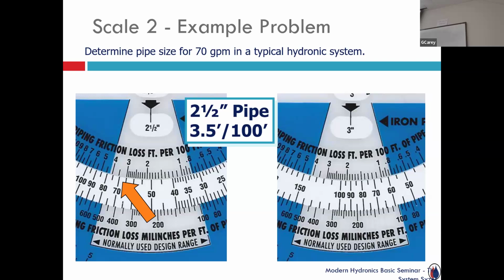So, from an energy consumption standpoint, what's the downside of going to 3-inch? Yeah, cost, upfront costs, installation costs, first costs, all of those. So do I spend a little less money with a smaller diameter? Operational costs might be higher, consumption of energy. Or do I spend a little more money up front, but over the life of the system, operational costs are maybe a little lower. So those are just things to be aware of that you kind of balance out. What's the goal? What are we trying to do here?